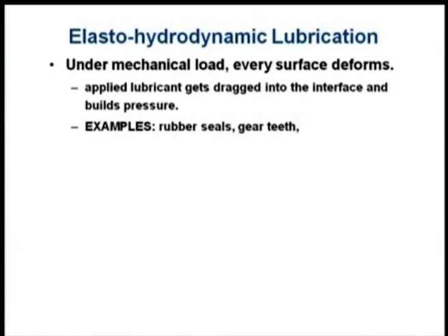Now, some interesting thing about elastohydrodynamic lubrication, or some sort of a mechanism which can be proposed. Under mechanical loads, every surface deforms. That is by and large true. Deformation may be at the nano level, but deformation will surely be there. And if there is a deformation, there is a possibility of dragging the lubricant into that interface. And if there is a dragging of lubricant at the interface, pressure will increase.